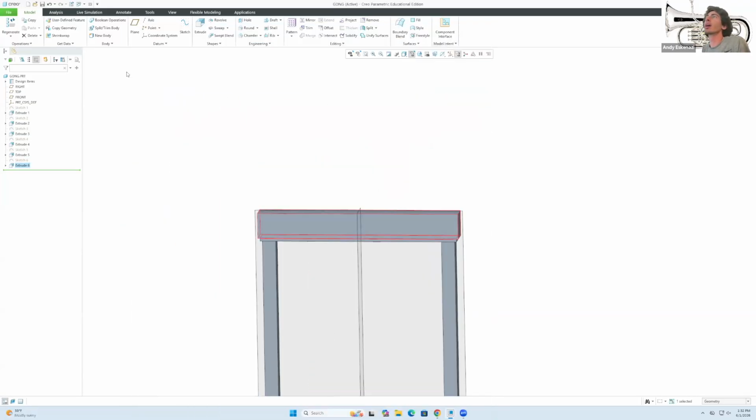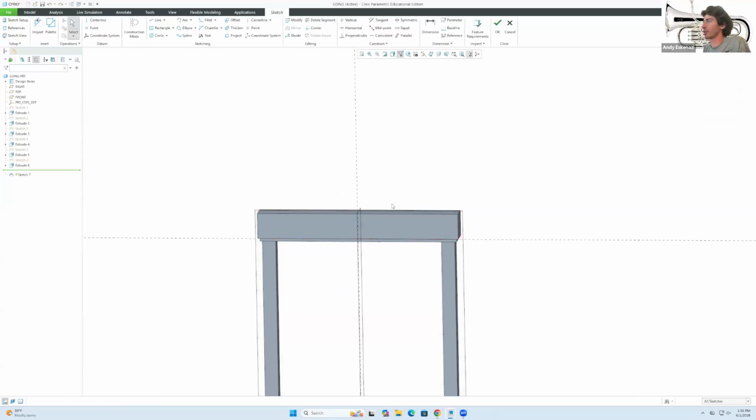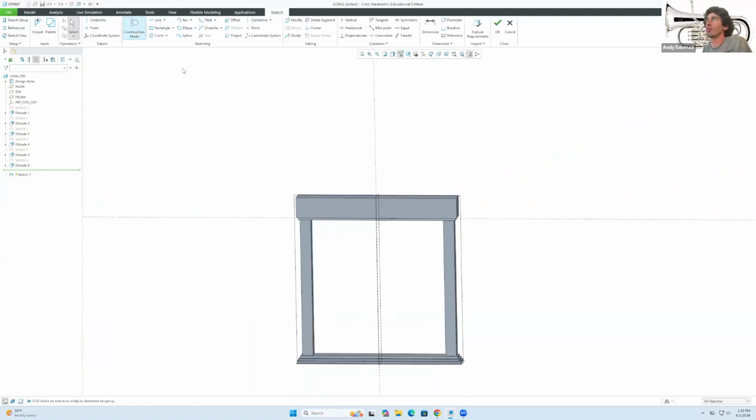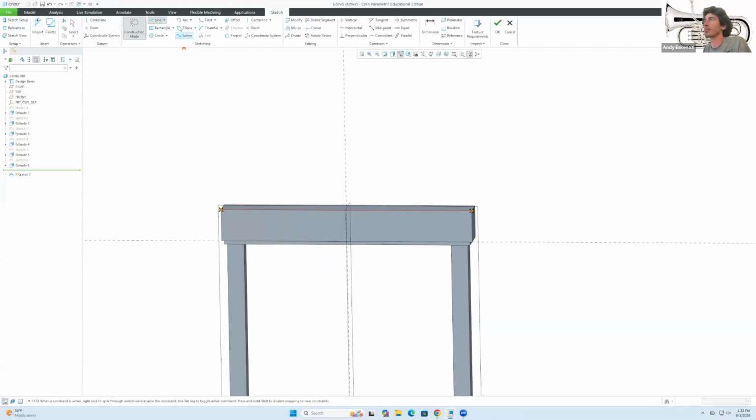And now that we have this and we can go back here, what I'm going to do is the following. I'll go here to sketch, to that face, sketch. And now we're going to use the arc for the first time. The one that I like is the 3-point arc, because I select that point. I select, oh, it's not letting me. And you know what I'm going to do? Let me first draw a construction line that will go like that. Excellent. Let's see.